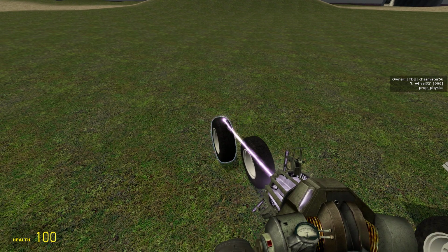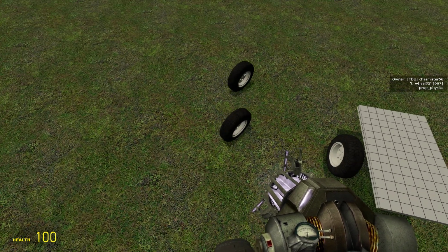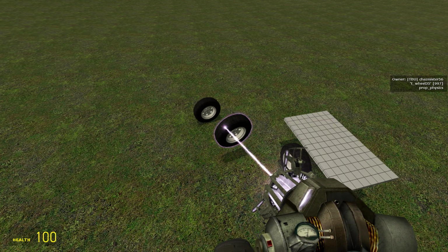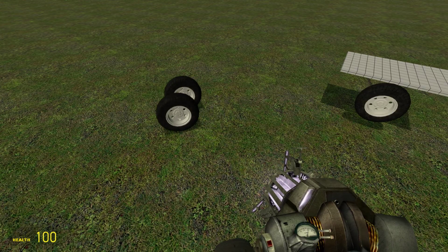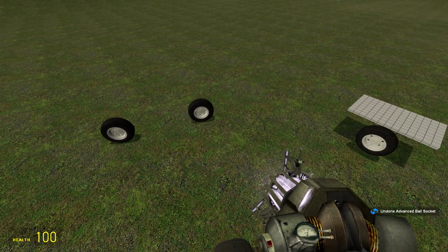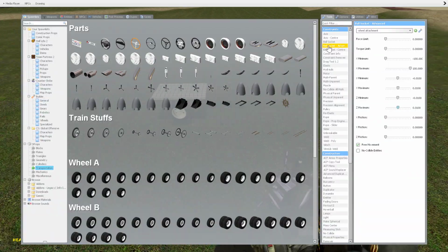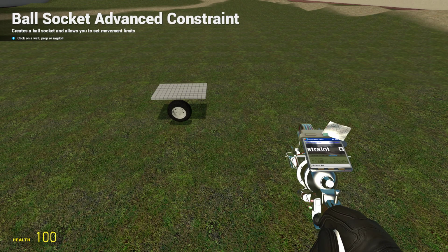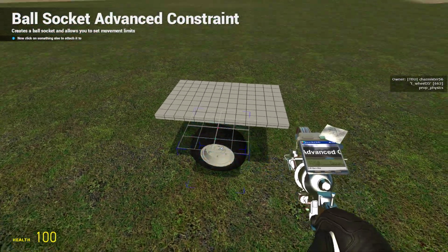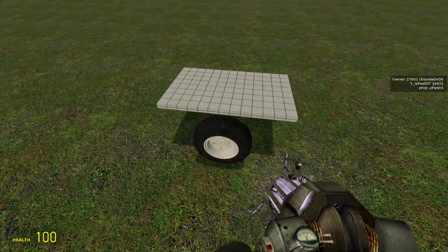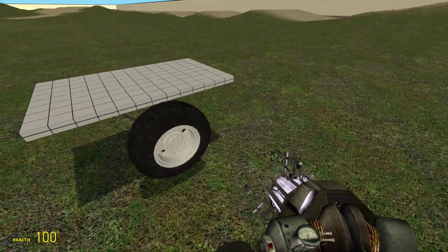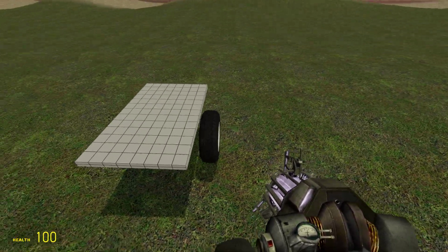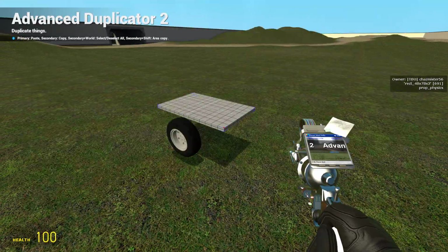And by that meaning, we can rotate these wheels in their X direction, and no matter what, they're always going to be able to roll. And it's going to work. That's the basic idea there. So that's why you want to use free movement on your suspension. Now we're just going to hit this. Doesn't really matter the order. Doesn't matter where you hit it on the wheel for free movement. It just locks both of these props to your ball socket specifications.